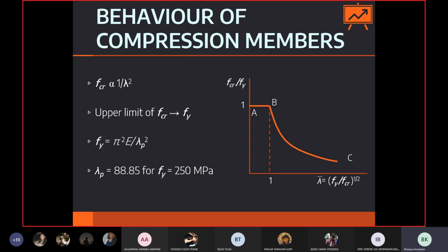And then eventually, after about 200 years and a lot of study, we realized that this is a curve for a perfect column. But actually, there are a lot of imperfections in columns that are actually built. We talked about a few imperfections before. The column might be initially crooked, or there might be certain accidental loading that we're not accounting for in analysis. Or when the column comes out of the mill, there might be some residual stress in that column.